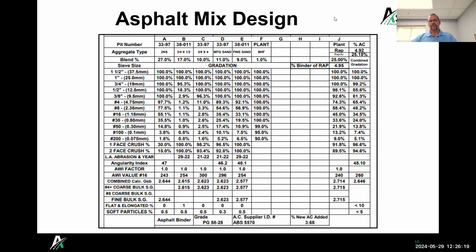So what we did was, we design at 4%, let's regress to 3% with liquid asphalt rather than just designing at 3%, because your aggregate structure, fines and things like that, you can close up those air voids that way and not add any more liquid asphalt to it. And we felt like that wasn't going to help our durability issue. That makes sense.